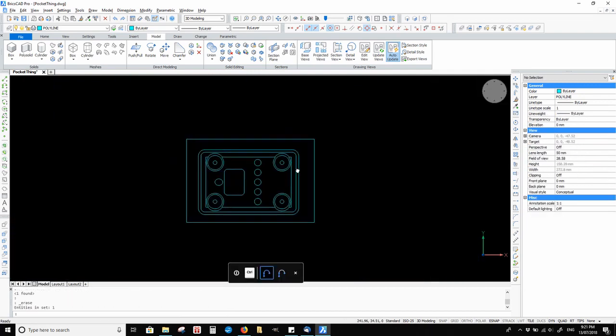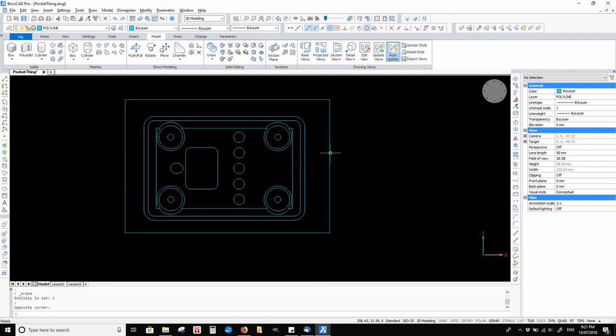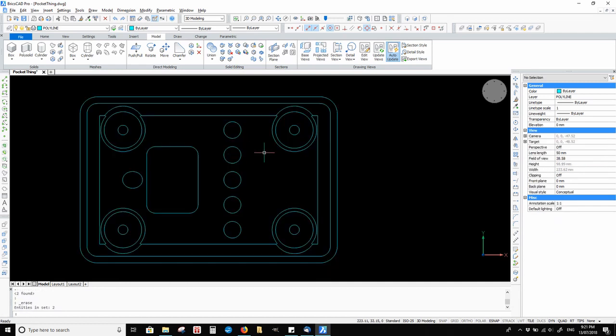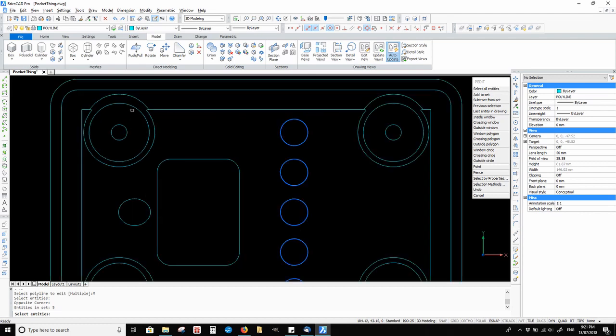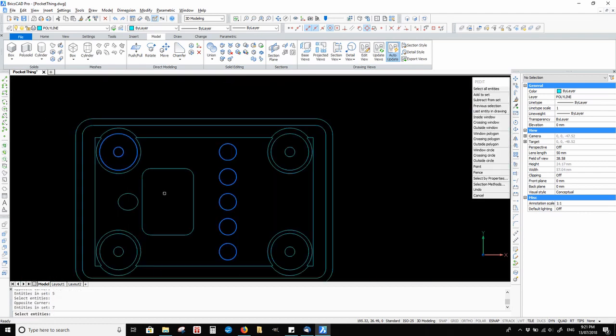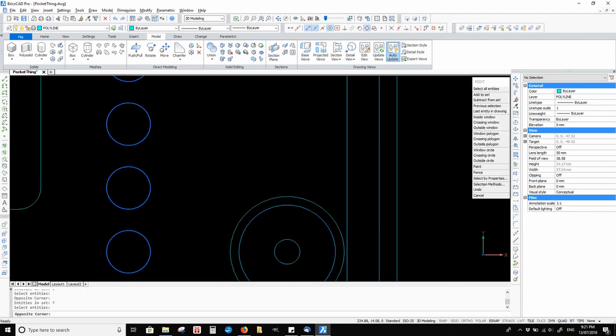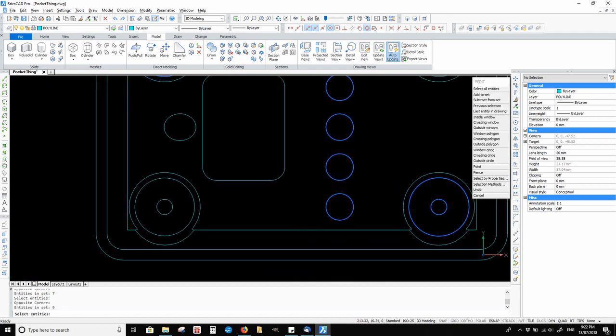Now comes an important part. We will edit the polylines at the circles with the polyline edit command. We want to use the fit option. This turns the straight polyline segments into curves of best fit. Basically, it makes the circles truly circular and not polygons. This allows us to measure circumferences and find center points.